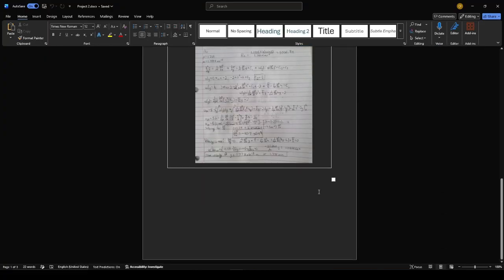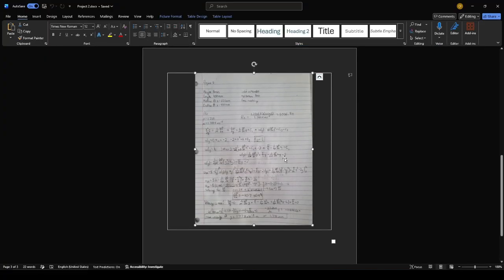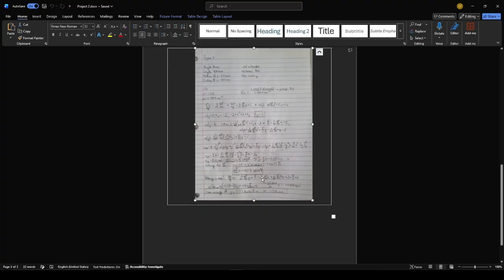We can see in here that I did some math and I calculated that the pressure difference will be around negative 107.364. So we are quite close to the expected value. So the theory and the measured results are very close. As you can see, this is the Reynolds number that I calculated. It is well under 2,500. And these are the error and the values that we will be using to measure this flow.